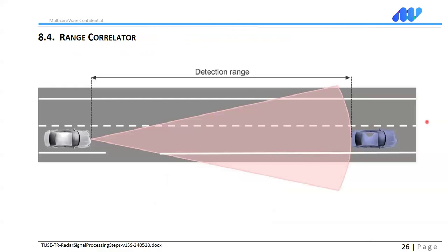It finds the correlation between the transmitted signal and the received signal. As normally, for any type of correlation, it gives a peak at the point where the target is. Since the reflected signal is a delayed version of the original, when you take the correlation, it gives a peak at the exact range point for the target.